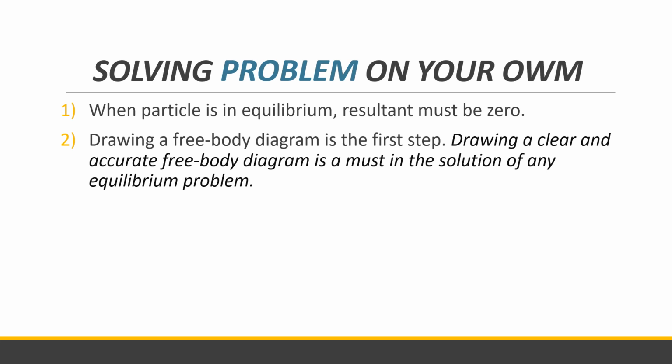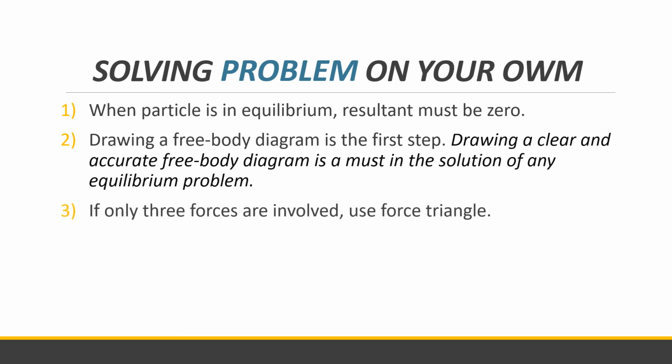Drawing a clear and accurate free body diagram is a must in the solution of any equilibrium problem, kasi na-simplified na yung space diagram into the free body diagram, and mas madali natin maintindihan yung problem. Since we can only see yung forces at yung mga magnitude and direction ng forces, that is how important yung free body diagram natin. Next, if there are only 3 forces involved, you can use a force triangle, mas mabilis magsagot.